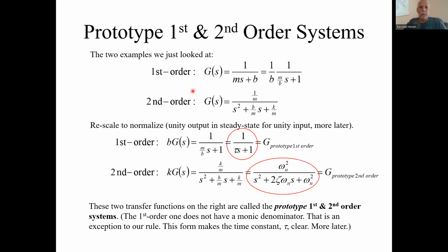But we looked at some physical models already. This first order system up here was a result of a mass damper system that actually didn't have equilibrium, but it was first order, meaning the differential was a first order differential equation. You can also look at this denominator, and the highest order of S is its order. So this is S to the 1, so it's first order. This was the mass spring damper system equation. See this 2, second order.